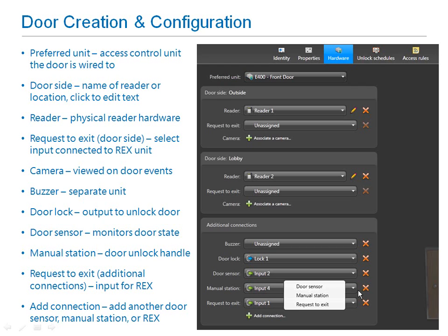The manual station input is connected to an emergency release handle connected to the door, which should immediately unlock the door in case of emergency. If this is wired properly, this is done directly through the door controller. We have the input here just to monitor when it was done and to advise the operators that a manual release station was activated by turning the door icon yellow.